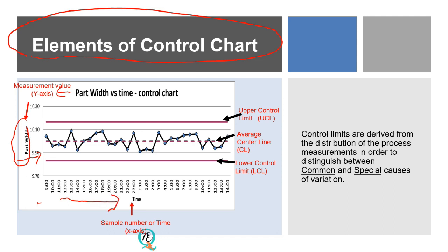This means that we are monitoring the trend of the measurement value against time, how it performed during the time of the process itself. We will need to calculate the upper control limit, the average, which forms the center line, and the lower control limit. These are actually measurements of variability, but with a slight tweak to adjust to the way the control chart uses the sample size itself.